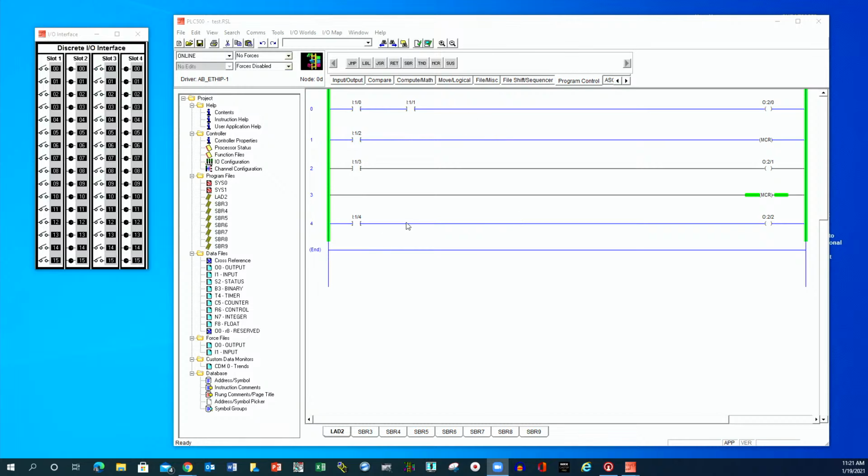So yes, basically what's going to happen is you're going to have your MCR fence here. This one here is going to be positive or true, and because there's no conditions, it's on. But the zone is not activated because the beginning one is not. But if I go to input 1, 2, I click on it. Now this zone is activated. That kind of makes sense. So when the start is activated, you're going to see the whole thing activate. And you could put input 1, 2 down here if you wanted. It really doesn't make a difference.